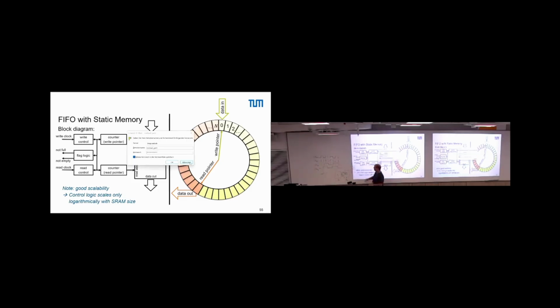If it's full, you evaluate in the write domain. If it's empty, you evaluate in the read domain. In that case, the critical part is the first write, because the first write here may be asynchronous in the read domain. Okay? Now we start reading.